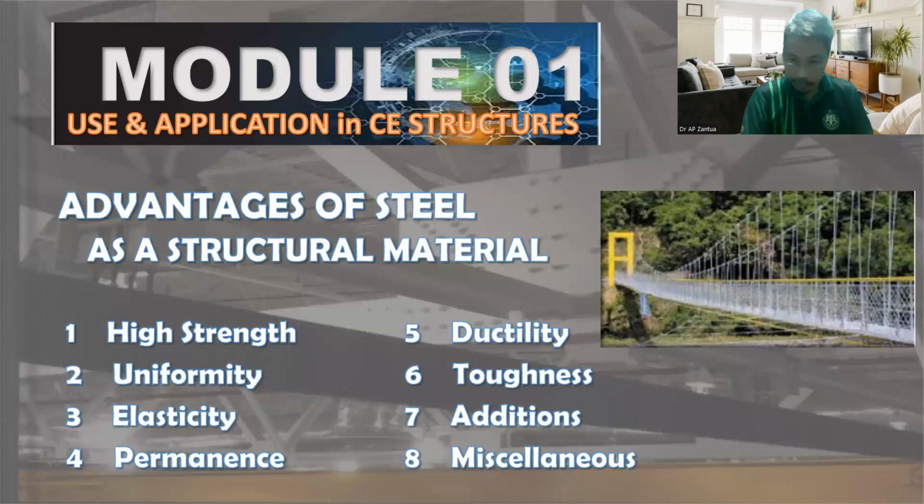If the pouring process would take about, for example, 3 hours or 2 hours, the later portion of the same batch of concrete mixture would have somewhat different characteristics, because it may have a substantially decreased amount of water already.